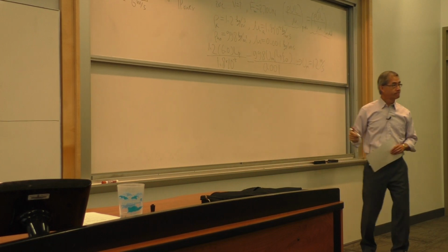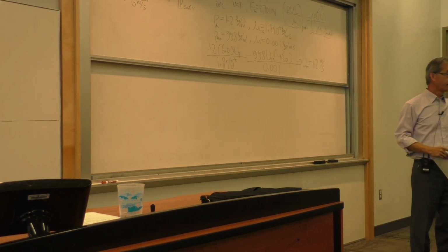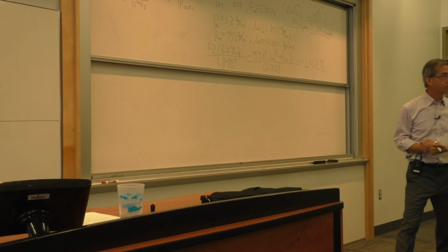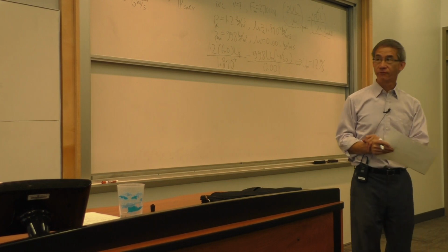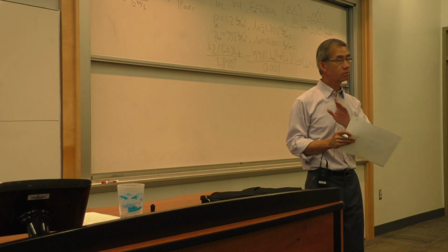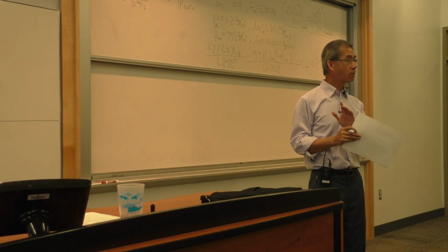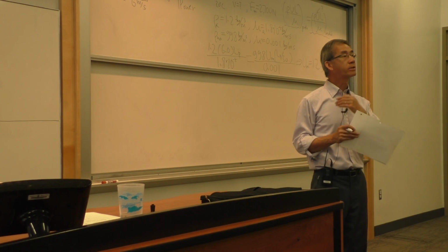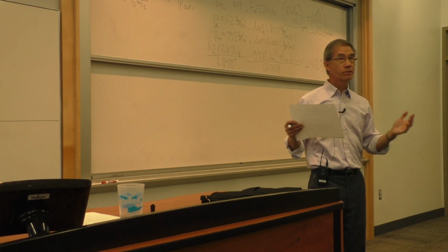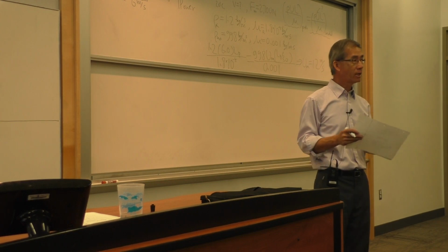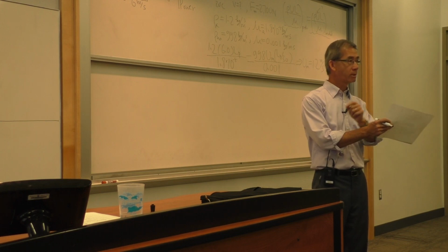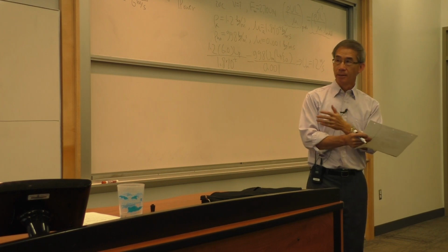Yes? So of the three types of similitudes that you listed over there, A, B, and C, which of those are covered by equating the pi terms? All of them. All of them? Yeah. Okay. The reason you have all three similitudes is to make sure your differential equations of motion are all cast in the same form. Then you non-dimensionalize it so that the equation has no units. In going through that, all the pi terms will be matched and you are bound to have the same physics between the model and the prototype. Every pi term must be equivalent to each other between the model and the prototype. That's a detail that I didn't cover.